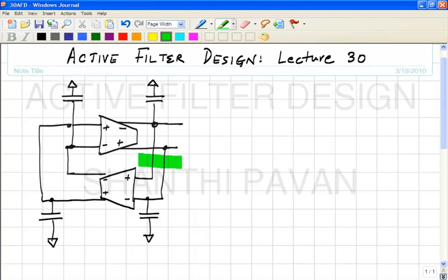For common mode signals, what happens? There is positive feedback simply because as far as common mode signals are concerned, both the nodes are basically the same, and if I yank the input common mode up, the output common mode will tend to go down, and the next transconductor's input common mode is the same as the output common mode of the previous transconductor. So, this forms a positive feedback loop, and the single ended equivalent